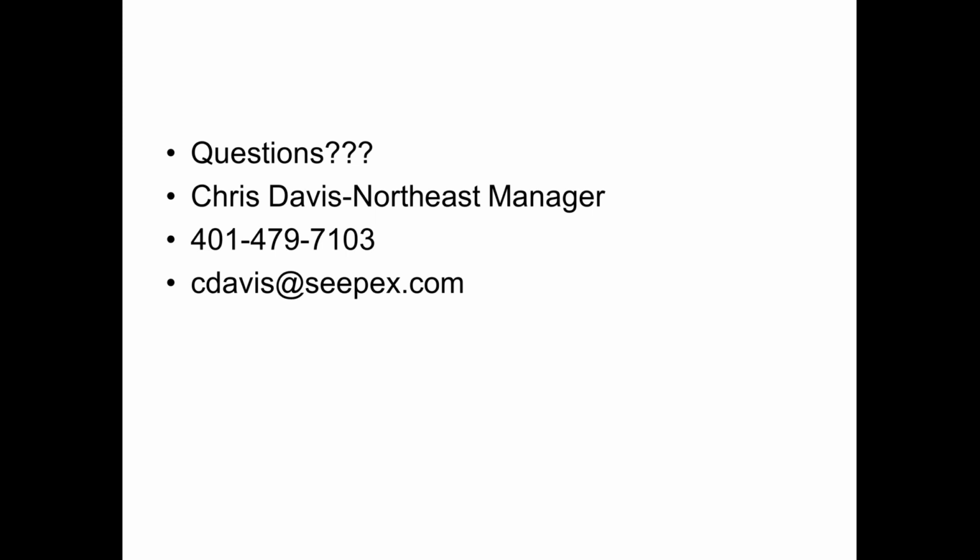Okay. Thank you. Number 2, are progressive cavity pumps cost competitive with diaphragm pumps for chemical dosing? No, I would say that diaphragm pumps would be on the lower end of initial cost of ownership, but higher end on the OPEX costs of ownership. So the initial purchase price of a diaphragm pump would be lower than, let's say, a peristaltic and a progressive cavity pump. But when you look into the cost of ownership, including parts and labor, a progressive cavity pump may show some savings. When you look at initial costs, a progressive cavity pump would be head to head with a peristaltic or a hose pump on the market.